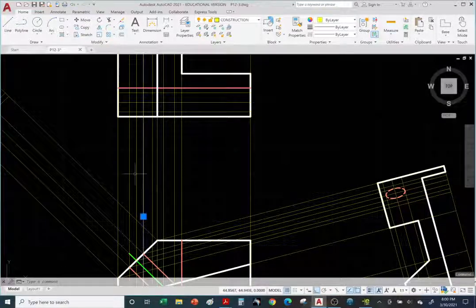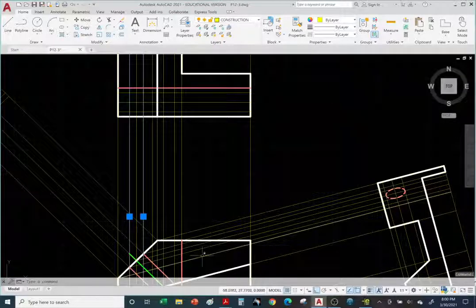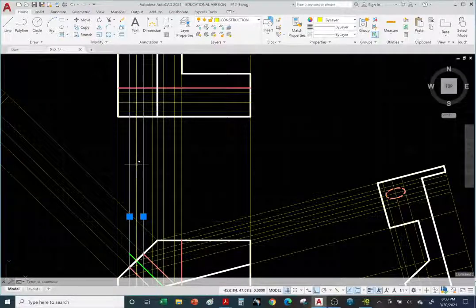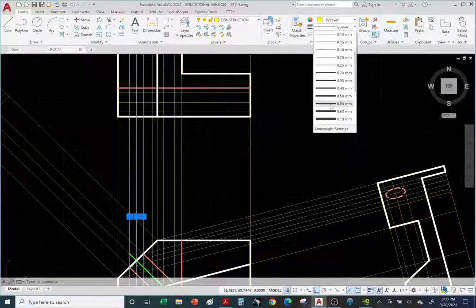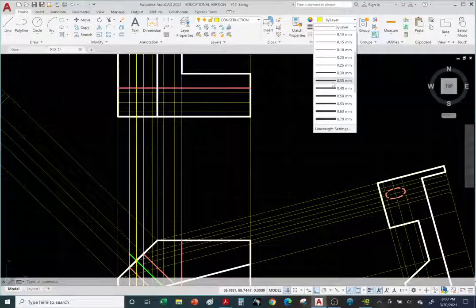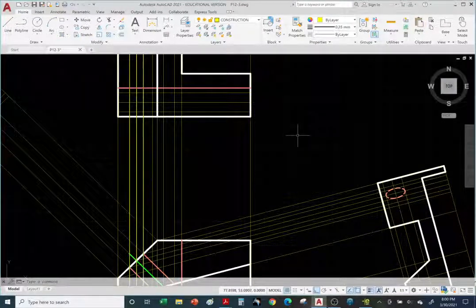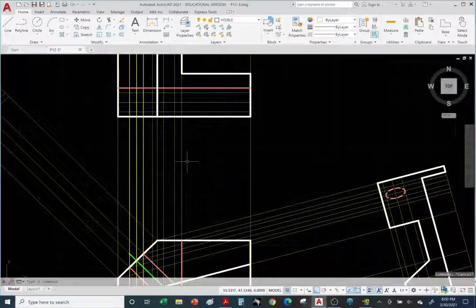These construction lines and this construction line will define our center mark and our diameter for the hole, our quadrants. Let me make these a little bit thicker so they stand out a bit. Okay, there they are. Hit escape to deselect.